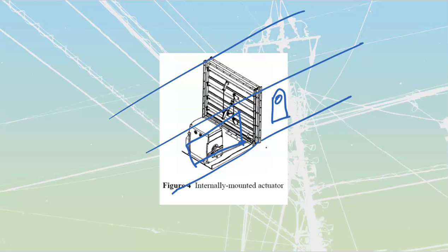Most of them are also going to be powered to actuate and spring returned. Not all, but a lot of them do that, which means that they will have a default position. The spring return does not mean that it will necessarily spring closed. It might spring open in some cases, whereas others are going to spring closed. That really depends upon the orientation. These tombstone style actuators that you'll see on the side of ducts are a through shaft, and based upon the rotation that you place them, physically, I could take this thing off, spin it around, and put it back onto the shaft in the opposite direction. That will now hold the spring pressure in the opposite direction. Makes them really handy for setting stuff as open or closed.